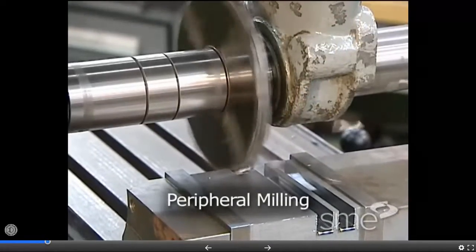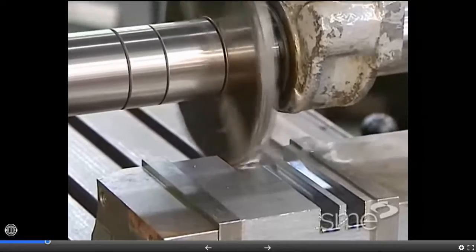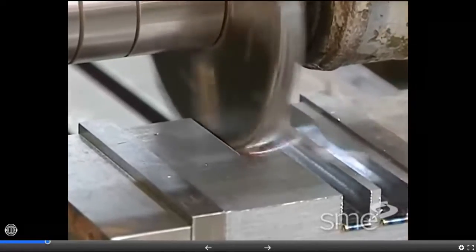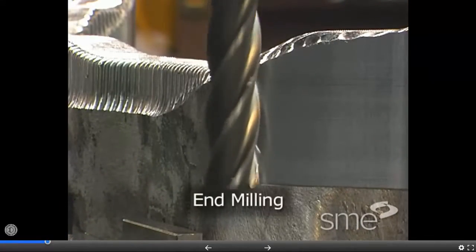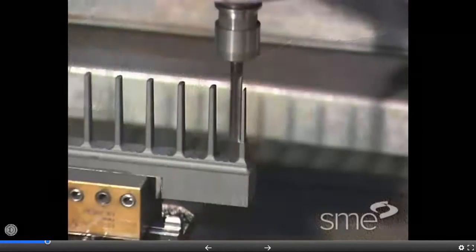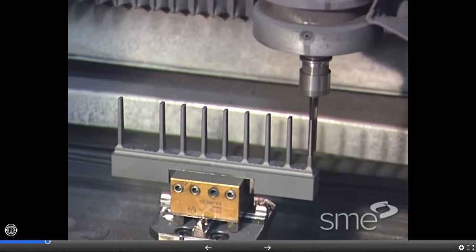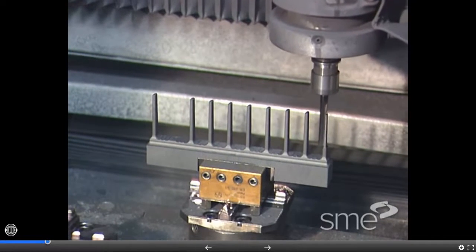Peripheral milling cutters have cutting edges on their periphery, which are parallel with the axis of rotation. Peripheral milling is useful for creating long open slots and forms. End milling cutters are round shank tools with cutting edges on their periphery and end. The axis of rotation is perpendicular to the surface produced by the end of the tool. Cutter size is defined by its diameter and cutting depth.